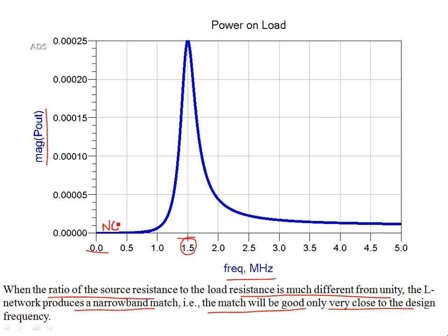But at high frequency, you have a mismatch of load and source impedance. Actually, at high frequency, this circuit pretty much reduces to just your source resistor of 1000 ohms with, let's say, an ideal voltage generator.